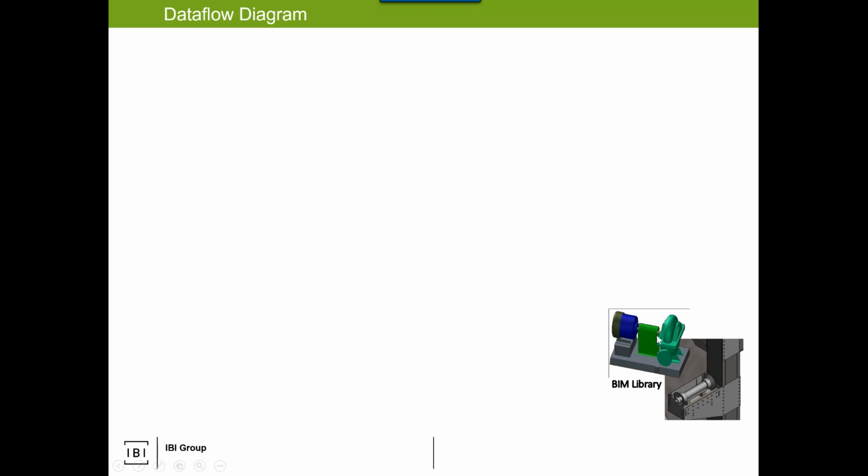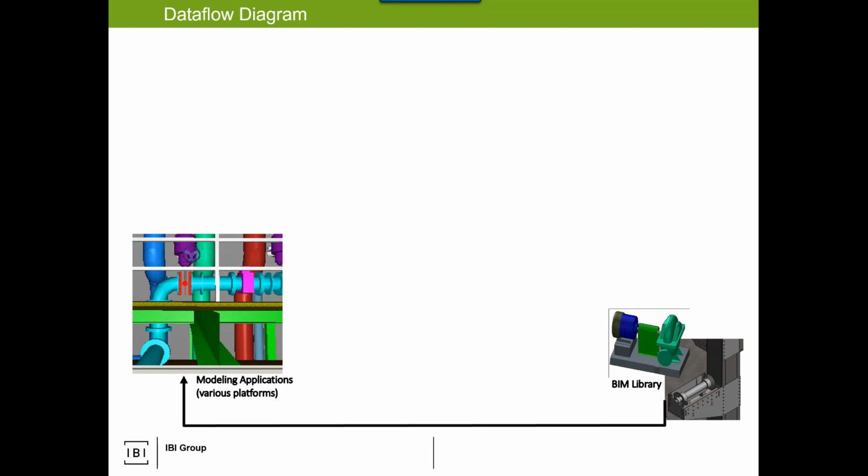And mechanical equipment is my favorite because you want to show enough to know what it is. You don't want to get so complex. I had a coworker once who used to model the buttons and the flip switches and a whole bunch of insane stuff. We don't need that stuff. But with mechanical equipment, you often need a connector. So if I attach a pipe to here or a duct to here, will it size it properly? That's the most critical thing with mechanical components.